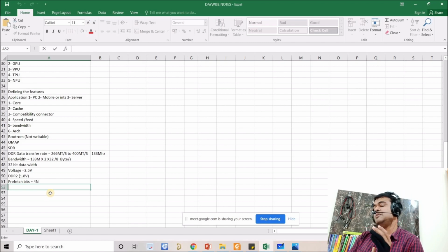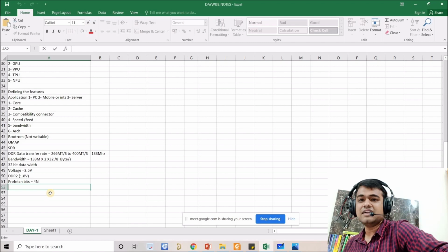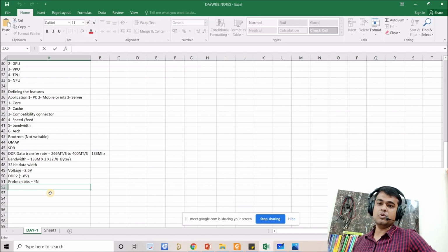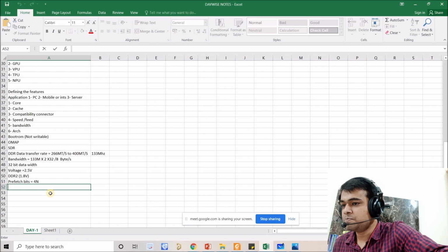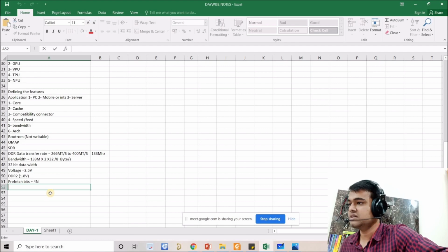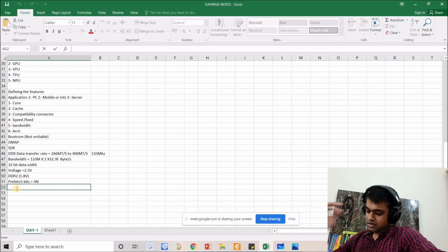So in case of LPDDR4, the multiplier is 16, which is really huge. If you calculate the maximum data transfer rate or bandwidth, it will come around 100 to 200 Gbps, right? It is really huge. And with that, the difficulty is increased for the designers, and we have to design a very ideal board, right? We don't have a lot of scope to play with the tracks. We don't have a lot of scope to play with the design rules, reduce the clearance, all of those things. We have to stick to the impedance planning and everything, right? So that is one thing.